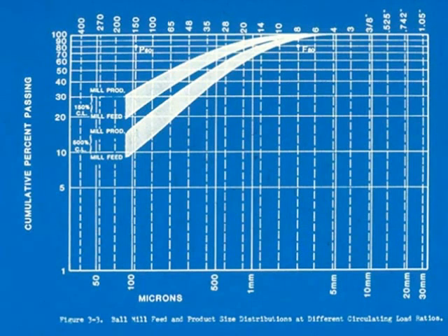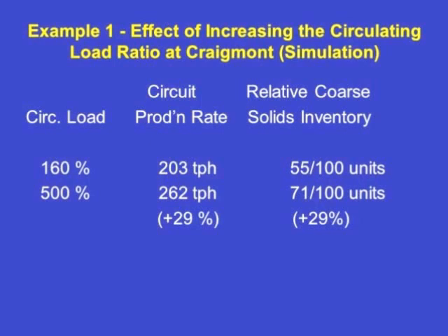That's the material that's getting the grinding energy. It's getting 85% of the grinding energy of our mill. Whereas with the much lower circulating load ratio, say 75%, only 75% of the material in the mill is coarser than the P80, and that's where 75% of our energy is going. And since I already knew previously how to manipulate and take this situation into this one, I had the ability